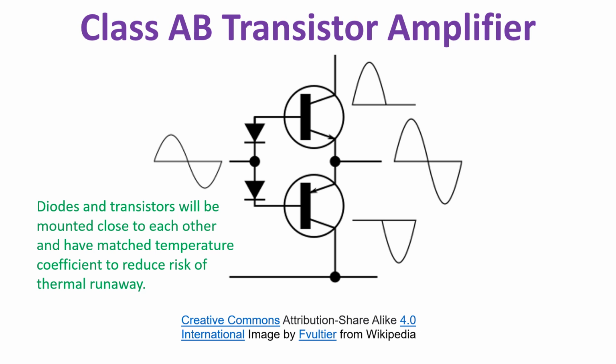In Class AB, the amplifier conducts a little more than half into a small part of the second half of the signal cycle. Hence, the region where both devices will be simultaneously nearly off is reduced. When waveforms of the two devices are combined, crossover distortion is greatly minimized or eliminated.